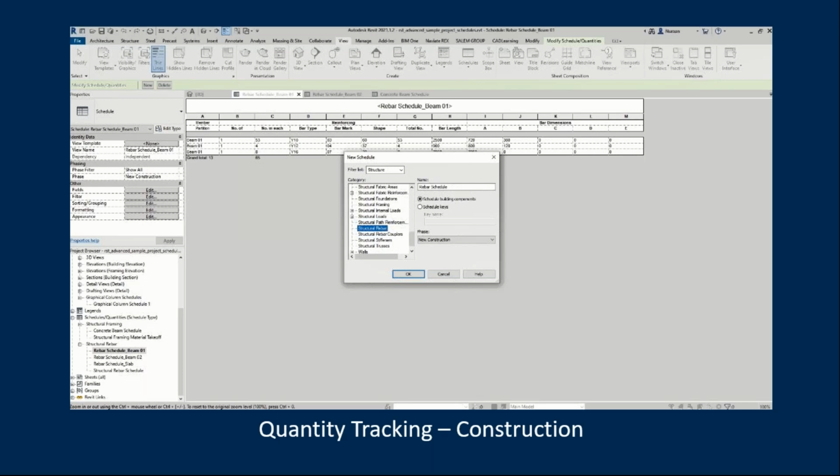So in this example, I'm going to demonstrate how to create a global parameter. There are quite a few steps involved with this one, but I'll just talk through it. This video will be available again on YouTube if you do need to review it. The global parameter I'm going to create is going to be the density for rebar, and that is used for all projects. With that parameter, I can then create a calculated parameter, use that density, and multiply it with the volume to get the mass of rebar in this beam 1.